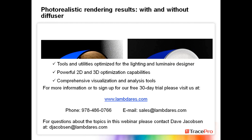I angled the reflector in this case so it blocks direct light from the LED, but we're seeing reflections off the reflective and shiny surface inside the luminaire. So this could be glare, it could be something that's just not pleasant to look at. And here's the same orientation, same reflector, but now we add the diffuser, so we see a more uniform source of light, a little more pleasing, not quite as aesthetically jarring to the eye.